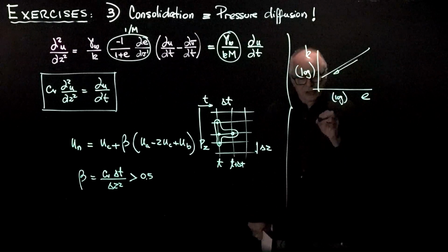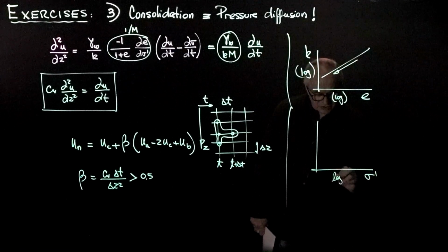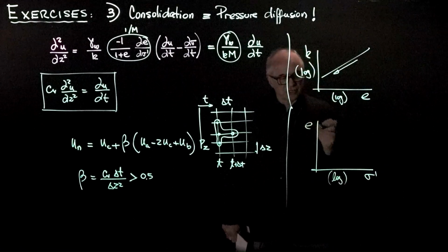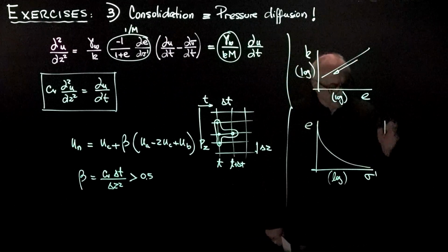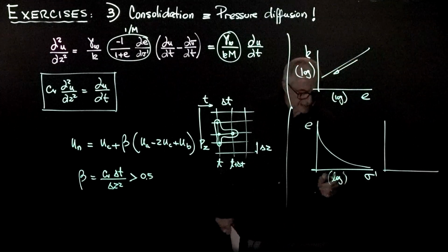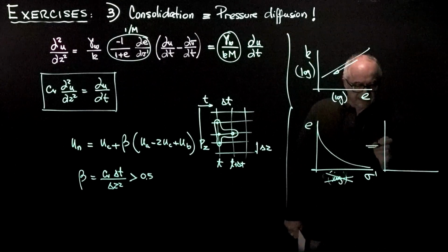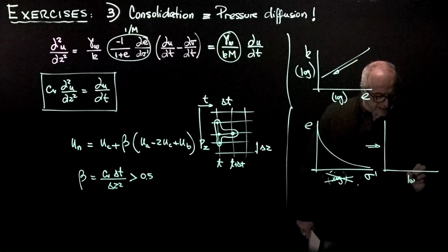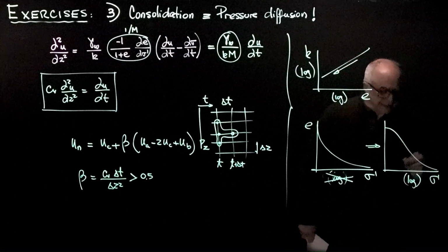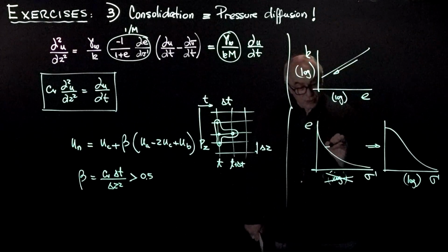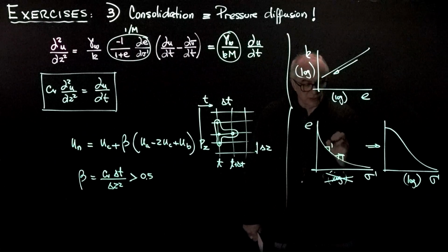And furthermore, if we plot void ratio versus effective stress, you remember that these tend to be asymptotic trends. Typically, we tend to plot them in linear scale. And if we plot them in logarithmic scale, we stretch the axis at the small values, and this is going to look like that. Now, the slope, the secant at any point, is that constraint modulus that we are talking about.